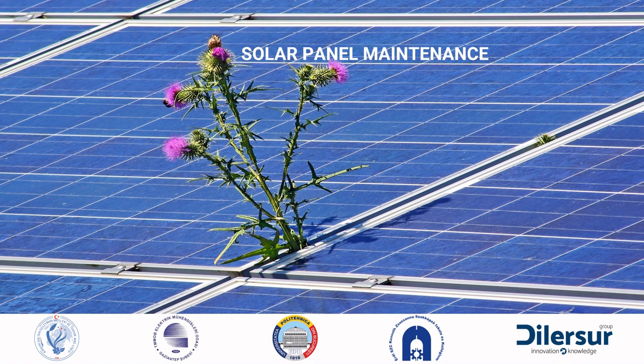Service of solar panels. Solar panel servicing includes various activities aiming to ensure their optimal functioning for a long time. These mainly comprise visual inspection, cleaning, functional testing, and some routine checkups such as corrosion inspection, vegetation management, shade control, wiring verification, etc.